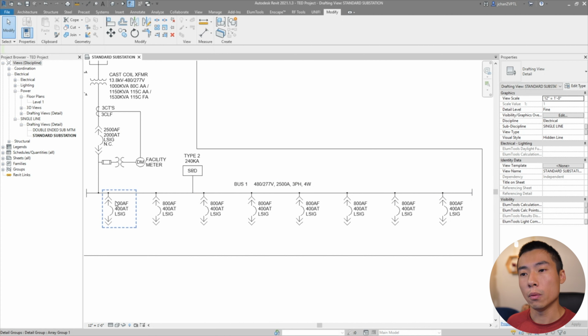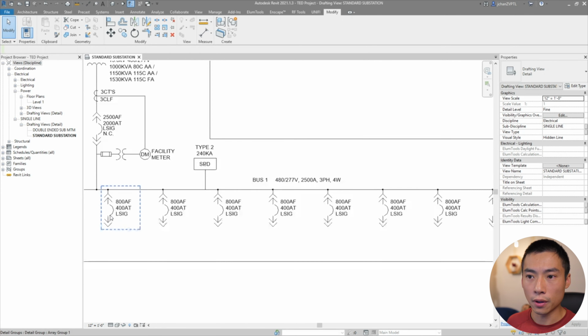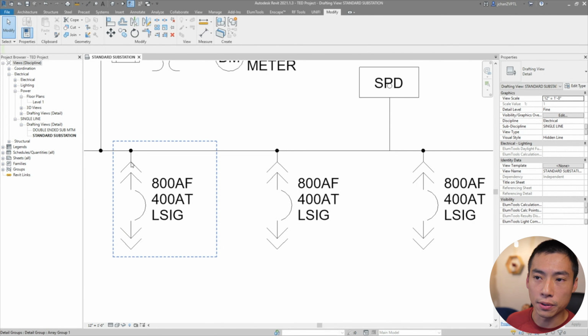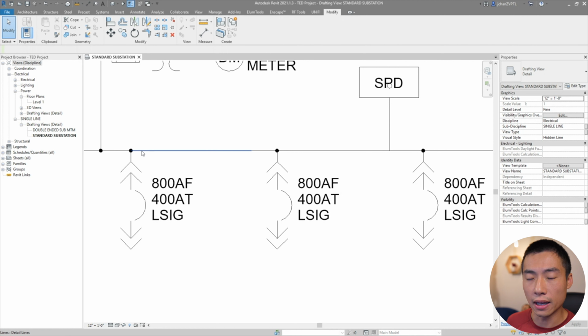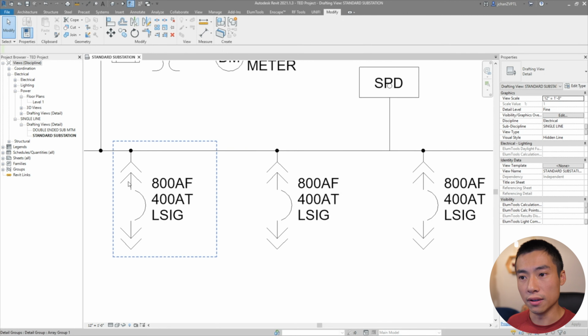And then from here, we have draw out breakers, which you can tell by these little stabs. So this stab is like the receiving end that you plug into the bus, and then this is your breaker that you can draw out. So the whole unit kind of pulls out, and it's basically like a big cube.